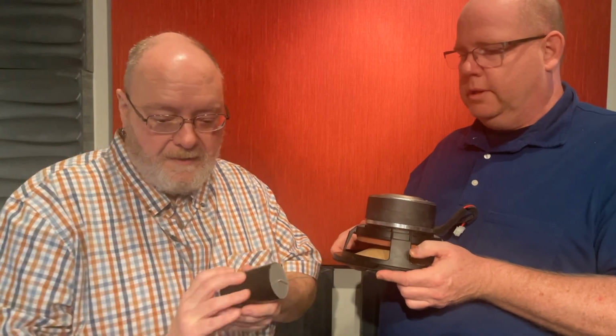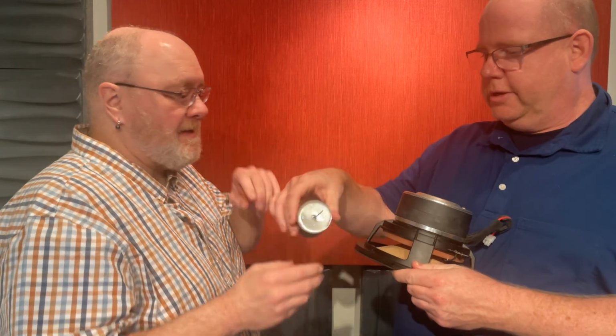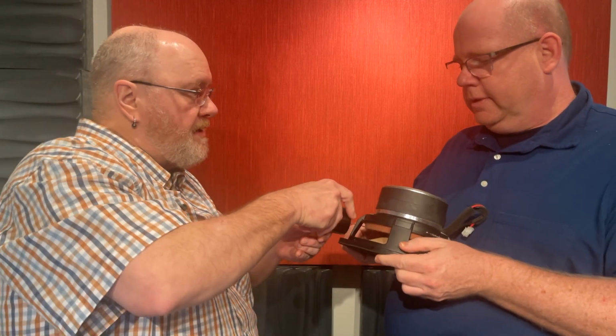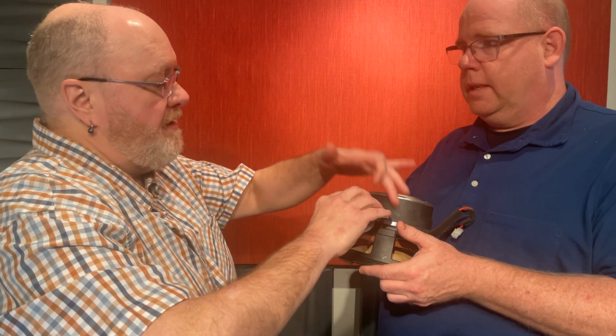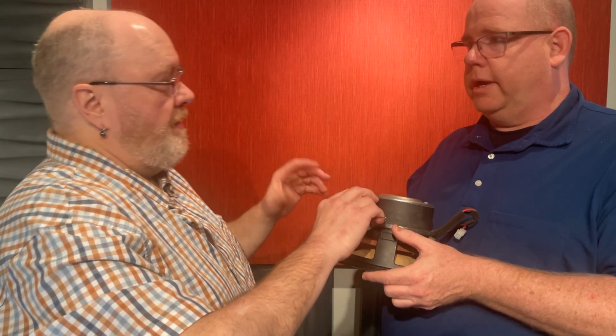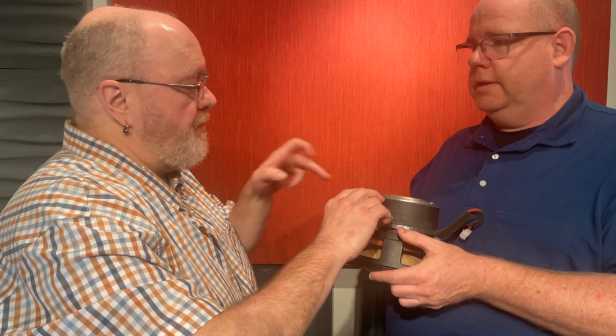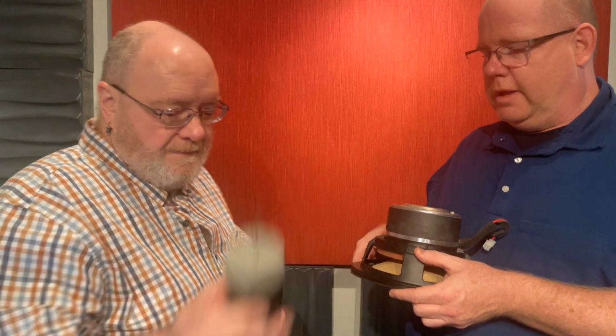But what happens if we do it the other way? If you take that series capacitor and put it in parallel, that means it's hooked in across the plus and minus. It's basically called a shunt at that point. It takes the same high frequency information that would have been delivered to the driver and runs it through the capacitor into the negative side and shunts it. It just goes away.